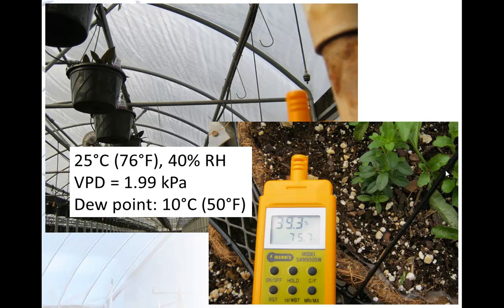Remember, I mentioned to you that this picture was taken from an Ohio greenhouse in early spring, and the outside temperature is about 0 degrees C or below. Therefore, the outside temperature is lower than the dew point, so condensate forms on the roof. To prevent dripping damage, the best approach is to drain away that condensate on the roof instead of dehumidifying to further increase VPD, which may damage plants and use a lot of energy. The best approach here, again, is to drain away the condensate.